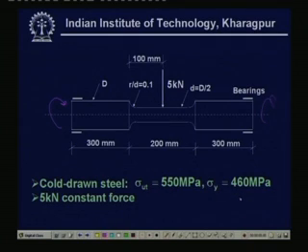You can easily understand that the fibers are getting completely reversed loading. And what type of loading is it getting? The predominant loading coming into the picture is the bending load, because of this 5 kilonewton the shaft will have a bending shape and it will try to rotate in the bend mode, thereby having a completely reversed stress cycle of a tensile stress and a compressive stress.